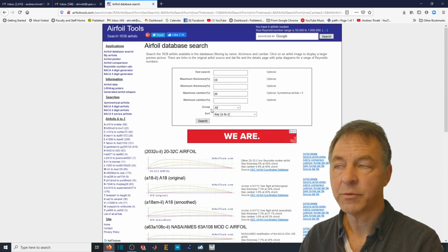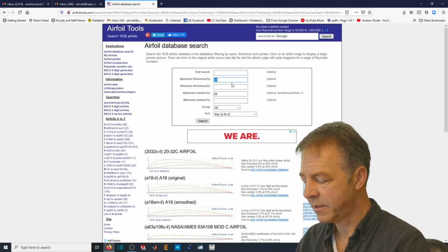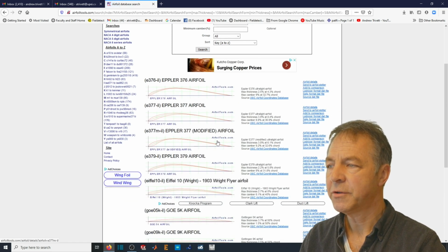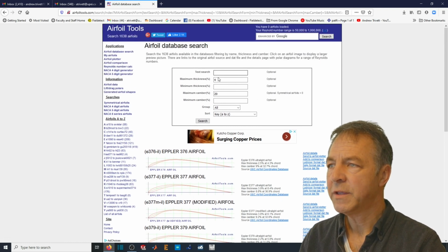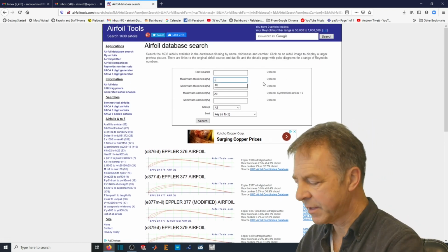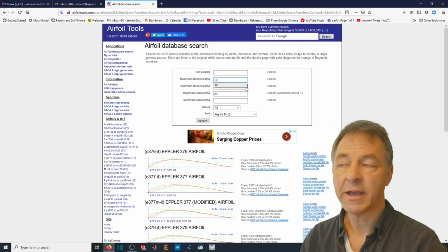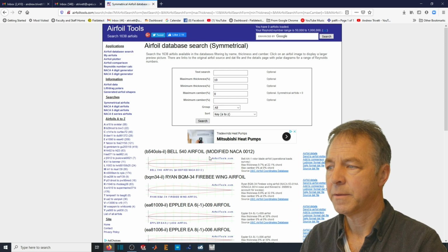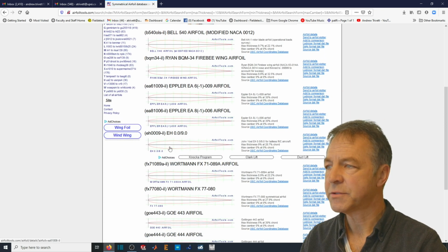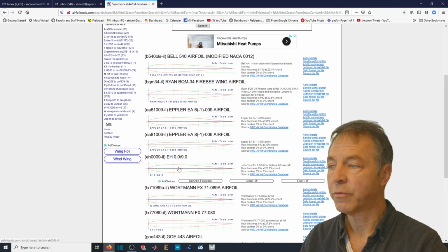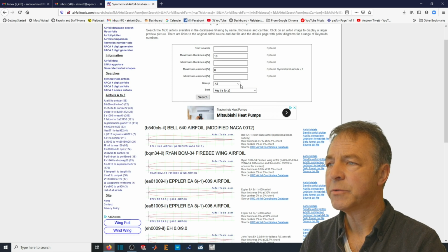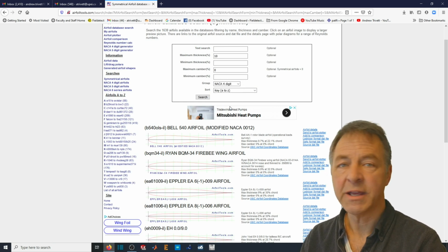And so you can see that they're even more curved. Now, if we wanted to have a very thin airfoil, we could pick something much more slender, and you can see the difference there. So these numbers of thickness are how thick the actual foil is itself, and camber, I'm going to pick 0. And from all of these different airfoils, you can see that there's a whole variety of them with different series that were tested. But I'm going to just look at the NACA 4-digit series.